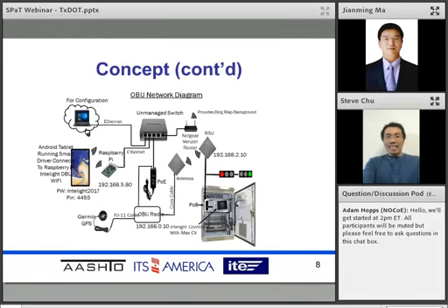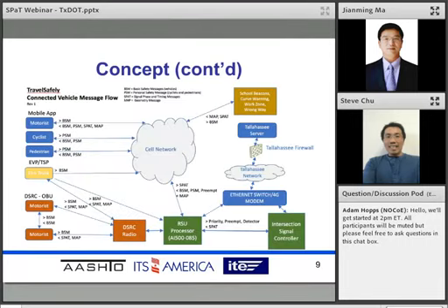So this is their system, but it is DSRC only, 100% DSRC equipment. And this one is designed by a cooperation between Applied Info and Kauai, a controller manufacturer. On this design, we started thinking, okay, there will be a transitional period between connected vehicles and non-connected vehicles. Then how do we address the vehicles that are not connected? So this is the architecture for the transition period.